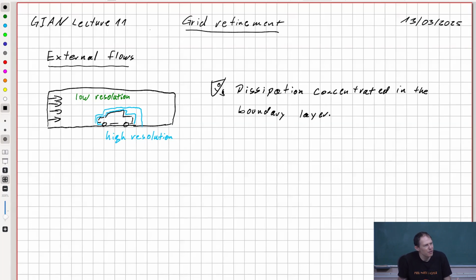Boundary equations are difficult actually to derive, yeah, so they can make a lot of mistakes. So you either have a very good boundary equation or you have a lot of resolution close to the boundary, or in practice actually you need both, yeah, because neither of the two is usually sufficient. So you have to have some specific boundary condition that mimics your boundary layer, and you need a high resolution on the surface, whereas